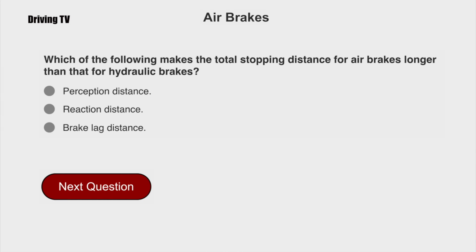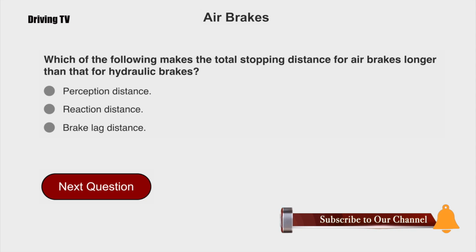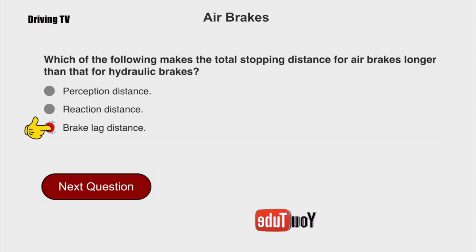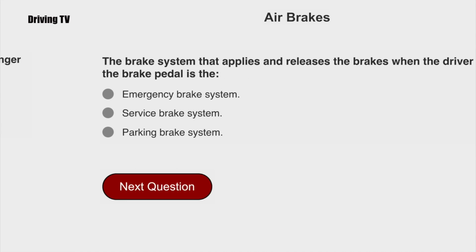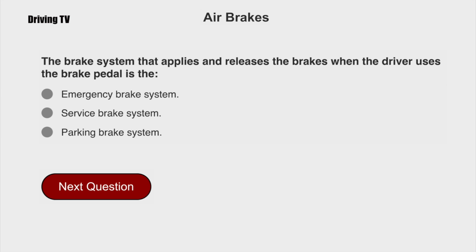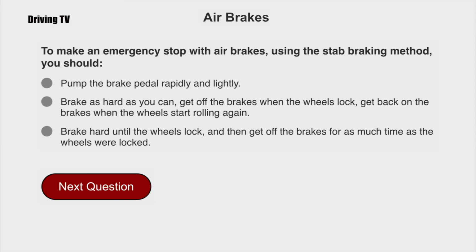Which of the following makes the total stopping distance for air brakes longer than for hydraulic brakes? Brake lag distance. The brake system that applies and releases the brakes when the driver uses the brake pedal is the service brake system. To make an emergency stop with air brakes using the stop braking method, you should brake as hard as you can, get off the brakes when the wheels lock, get back on the brakes when the wheels start rolling again.